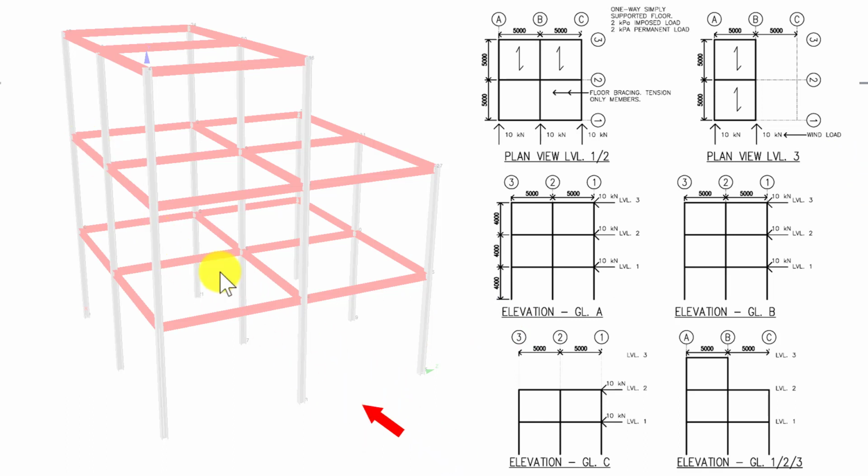And as a structural engineer, we then need to look at the mechanical engineer's drawings or the architect's drawings and then decide where can we put bracing. Where are there doors, windows, machinery, conveyors, equipment? Where are things that we can't put bracing in the way of? And then work around that, and also where are there foundations which we can carry load to, if not all the foundations are the same, because we will then need to increase the size of some foundations if there's increased load on them.